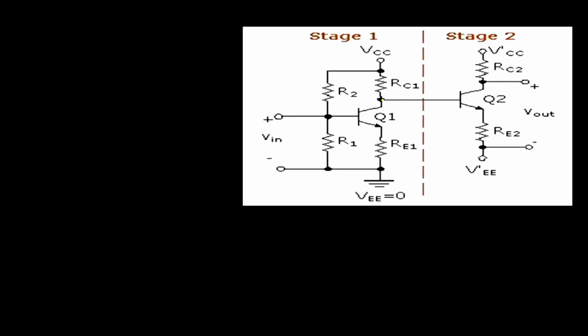Direct coupling is when you apply 2 different voltages to each part of the circuit and you directly join the input to the output without the capacitor to couple each of them. Because of this, you are forced to put another source voltage to the second stage of this amplifier.